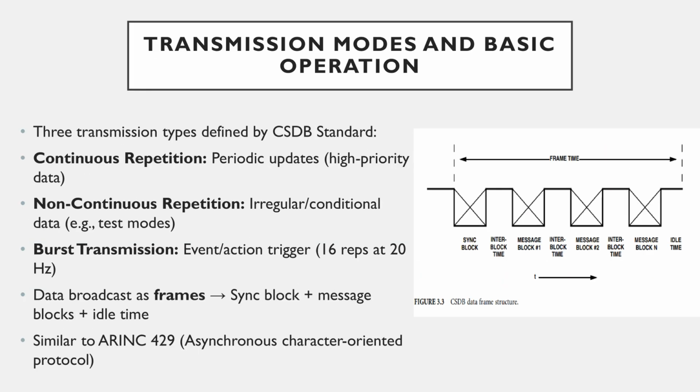CSDB supports continuous repetition for periodic updates, non-continuous repetition for conditional data, and burst transmission for triggered events. Burst mode repeats the same message 16 times at about 20 updates per second, similar to fault annunciation systems.